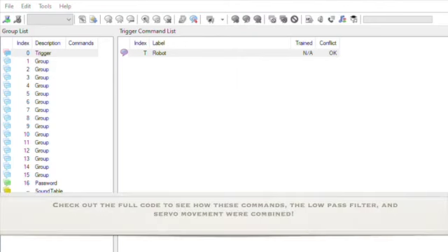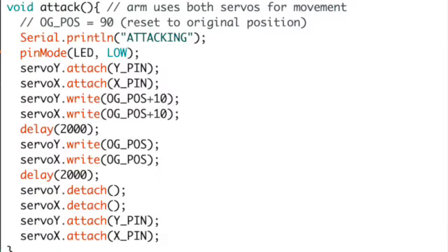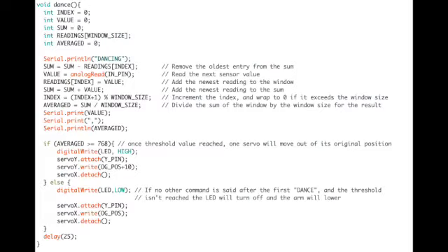I trained the VR module with 3 words: action, robot, and stop. Whenever I said action into the VR module's built-in mic, the servos would start rotating into the desired configuration for attack. We experimented multiple times to get the right configuration for this, as well as the configuration we wanted when the arm was just supposed to dance. This required setting the servos to rotate at different degrees at different timings.